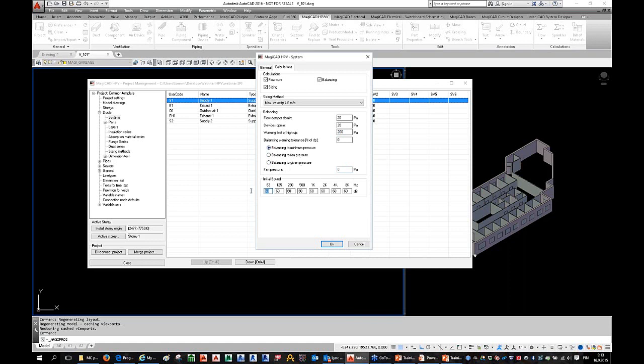And if you don't connect your duct to one of our air handling units or fans, then you can give the initial sound. You can basically simulate the air handling unit with this. You can give any sound here.